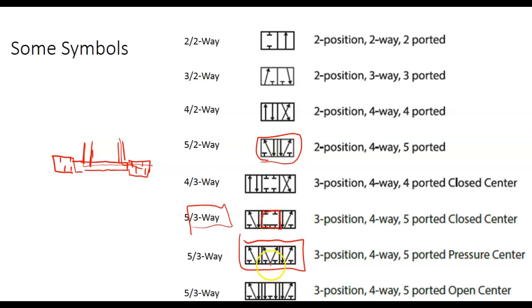So what happens is that when we're in the center position, and this is a double acting cylinder, this is pressure, so that's pressure. We're actually putting pressure on both sides of the cylinder. So what's going to happen? Wherever that sucker's at, it's going to do what? Stop. So this is what we have on the, they're simulating it on both the Festo and the Amatro line. I don't know why they didn't use one of these. So what they're doing, they're using two 3 valves, and they just put pressure on both. They turn both. We'll see it when we get there. So they're simulating these with 2 valves, but this would work perfect on pneumatics.